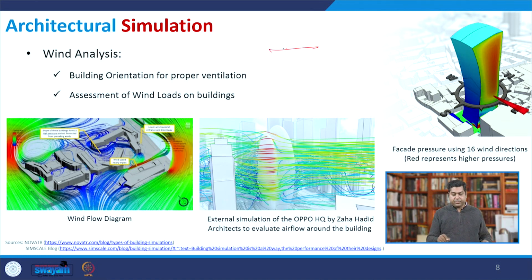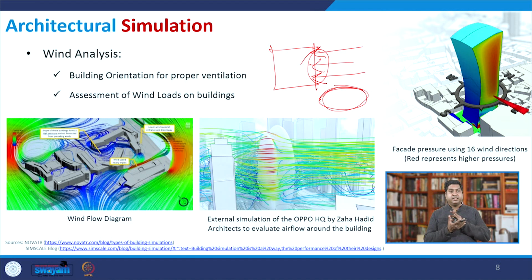Now whenever you have a surface perpendicular to the wind direction, that will create some sort of pressure on the surface. So for such reasons we also try to change the shape and orientation of the building, or the overall shape of the building, to give some sort of aerodynamic shape, the way we design bullet trains or aeroplanes. So there is some sort of aerodynamics coming into that discussion and consideration, where the wind can very easily flow, and it will not create the pressure.